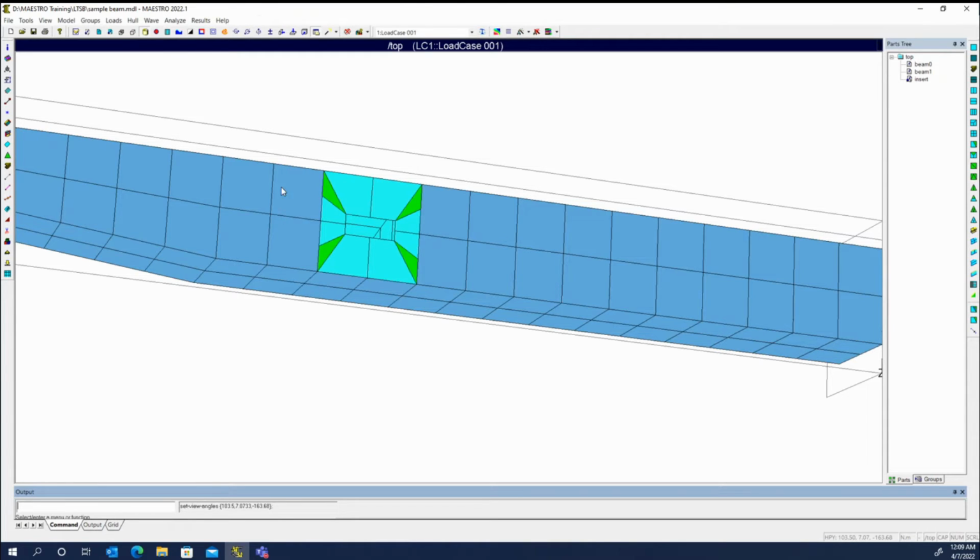On this element, which is in the same module as the one that we just split, Maestro will see that there's already a node there and it'll use it, so it won't create an additional node. If I move this node first, it's going to see there's nothing there and it'll create a new one, because it always splits at the midpoint.